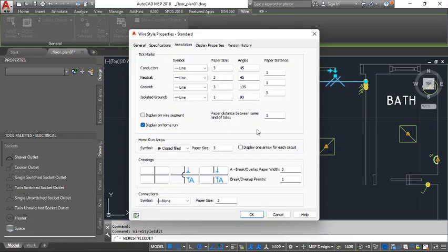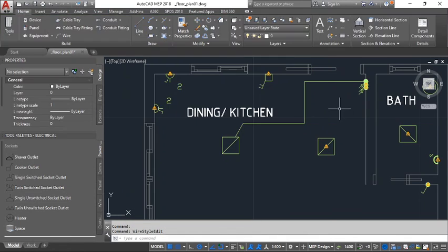Okay, we don't represent it in our diagram. We don't show any wire going all the way to the panel, but instead we use a home run to point anywhere. It just shows that it's at that point that we have a connection to the circuit breaker. Okay, so that is what the home run represents. So click OK, and you see those tick marks disappear.